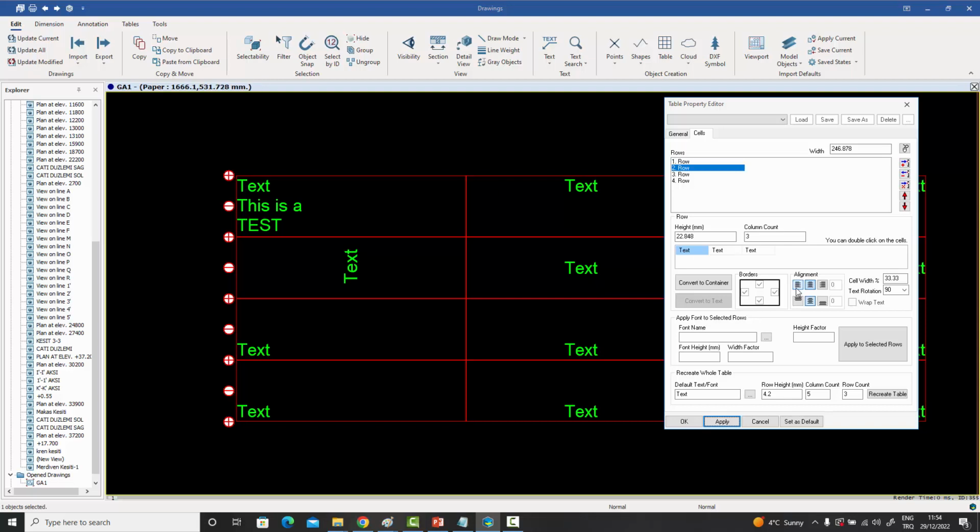If I want, I can change the location. I can put it on the left side or on the right side. And if I want, I can even give it an offset from this using this parameter. And this offset is then applied to the alignment. So as you can see, the alignment can be set from left, middle, right, and from top, middle, bottom as well.